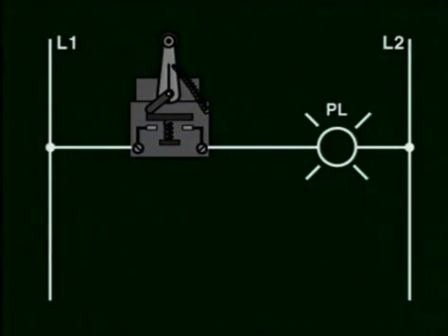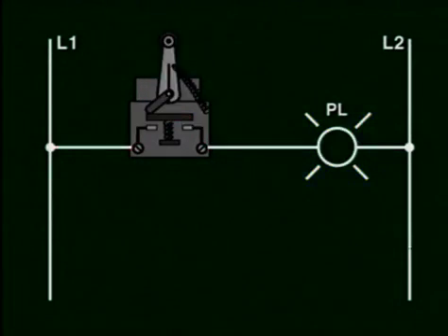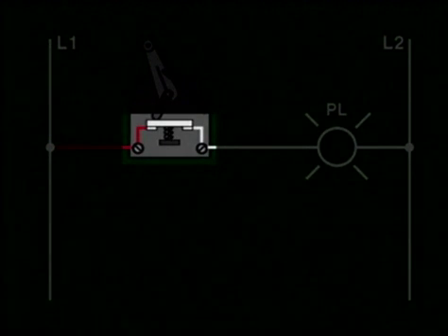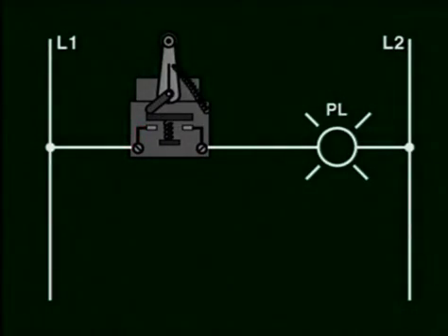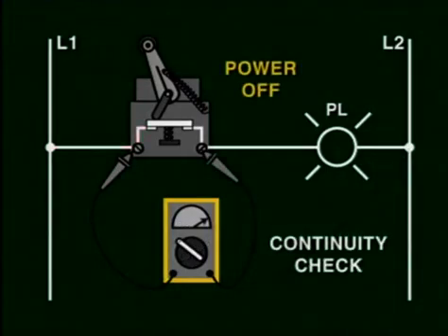The electrical troubleshooting of limit switches follows the same basic methods as those employed to troubleshoot a push button, whether the problem is with an open circuit malfunction of the contacts or a short in the switch due to an overcurrent fault condition. This troubleshooting is done with a voltmeter to check for voltage during contact closures, or with power off to check for continuity of the switch contacts.